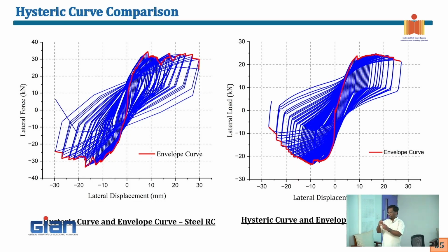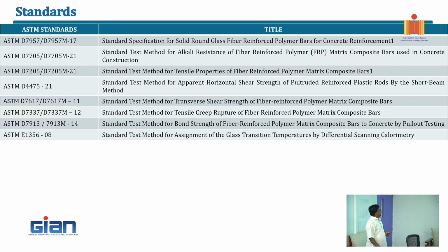This is member level behavior. Now I put GFRP rebar and concrete; at the section, they act together. When I want the member response, I have to integrate all the section responses, so it's a little complex and we cannot really say. But in general, the energy dissipation in a GFRP system is somewhat lesser than that of steel. Our goal is, when I add fibers, what will happen? The energy dissipation is going to get close to that of steel. It may be better also. We don't know. That's what we are working on.